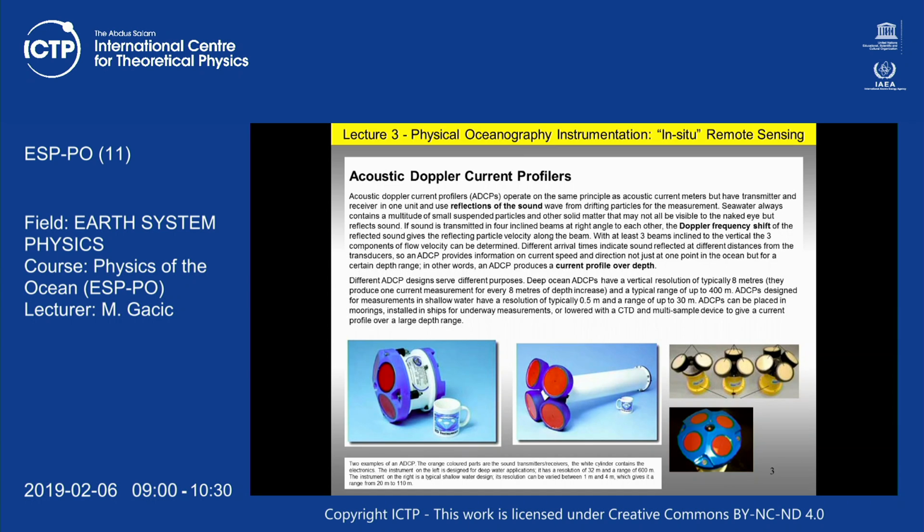We obtain also that the total transport in or out has to be equal. One inflow has to be equal to outflow on a longer time scale. Otherwise, the sea level in the Adriatic will increase. We obtain that the total amount of water which exits is on the order of 1 million meter cubed per second.